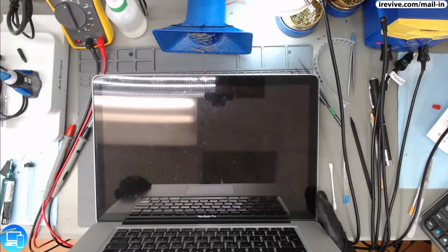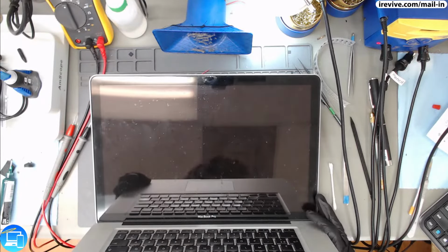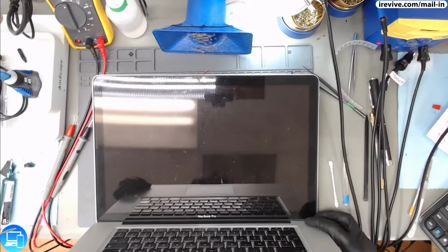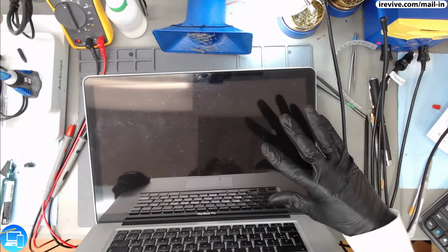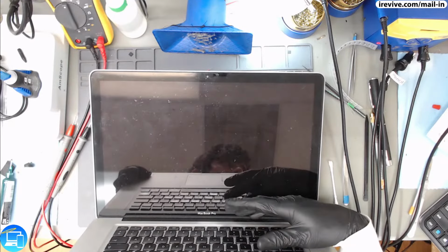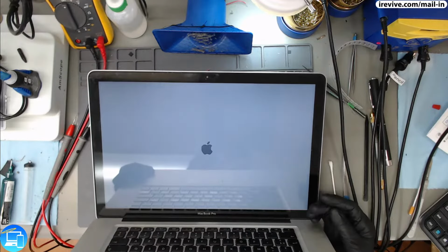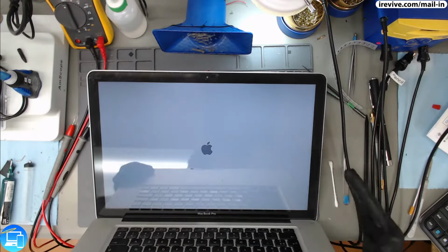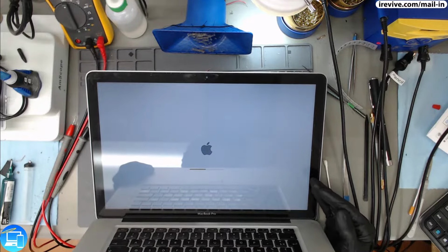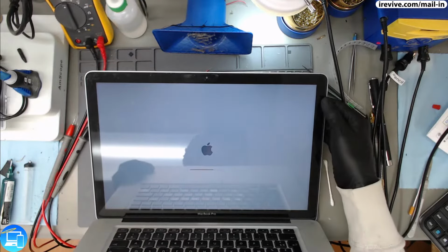Now, you cannot remove those resistors without doing the Gmux first. Yes, it loses power to the AMD graphics card, but if the Gmux has not been properly programmed to only use the integrated graphics card, you're going to break something. I've seen people just remove those resistors and call it a day, but the second you do a PRAM reset, this computer just stops working entirely. So you have to flash the Gmux with the DOSDude Gmux software before you can remove those resistors.